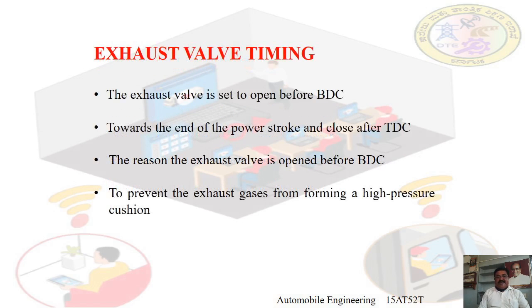The exhaust valve timing. As per the valve timing diagram, the exhaust valve is set to open before bottom dead center, towards the end of the power stroke, and closes after TDC, I mean top dead center.